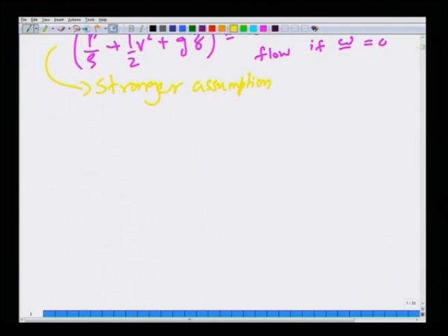We also pointed out in the last lecture that irrotationality, although being a kinematic assumption, is more likely to be seen at higher Reynolds numbers when you are far away from solid surfaces. So, we can assume the flow to be reasonably irrotational when the fluid flow is happening at high Reynolds number, but close to the solid surfaces rotational effects become important. So, we can imagine the solid surfaces to be sources of vorticity, and the vorticity will be confined close to the solid surfaces, but far away from solid surfaces at high Reynolds numbers the flow is largely irrotational.